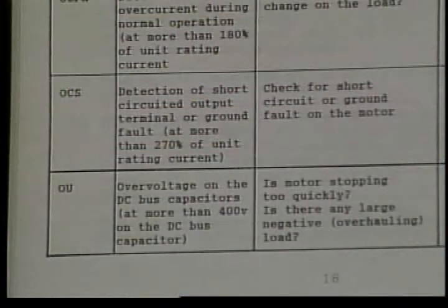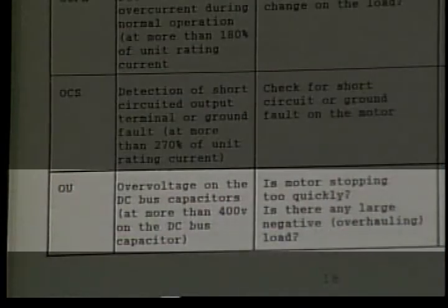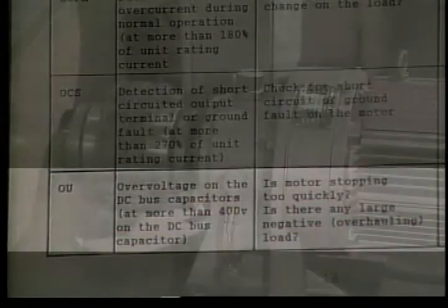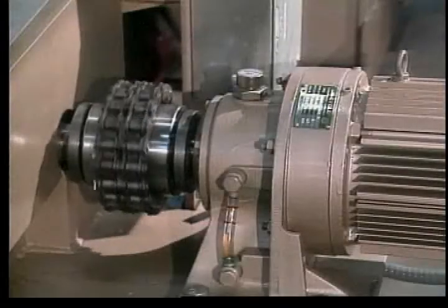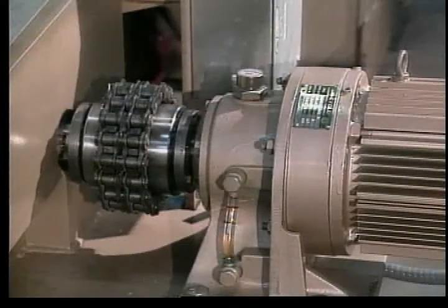When the load is very large, external resistors may be used to boost the braking capacity even more. However, if the load is too great, or if it is braked too frequently, the inverter may trip out to protect the capacitors and the resistors from damage. When this happens, the braking effect is lost, and the motor simply coasts to a stop.